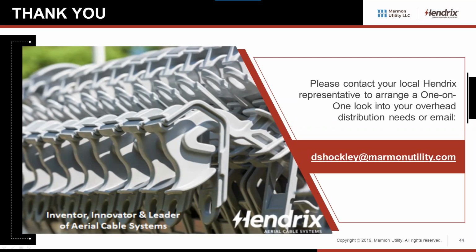So, when we switch underground circuits, what you do is you release a long landline capacitor into that transformer, and you may or may not have what's known as ferroresonance, so that the capacitance is equal to the inductance of the rest of the system. And then you have a resonant system condition. You have voltage waves going back and forth and overvoltages and possibly blowing up some equipment.